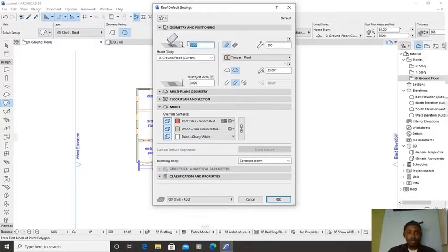That is the input you make here. My wall is 3,000, so I'll leave it at 3,000. If you're doing a multi-storey building, like 2 or 3 floors, it should be on the last floor. Or if you're just doing a ground floor, it stays on the ground floor.